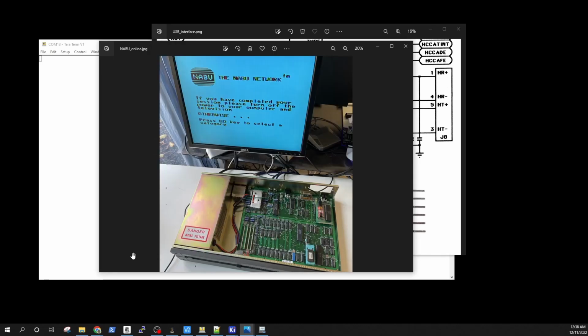That third way is to replace the operating system of the Nabu with some very simple resident operating system, typically referred to as monitor software. This monitor software is similar to what an Arduino is doing, where there's a small bootloader waiting for serial connectivity at the very beginning, just after reset. Once that serial connectivity is up, you can upload your code and it will execute the code that you uploaded. So that's what we're going to try and do today.